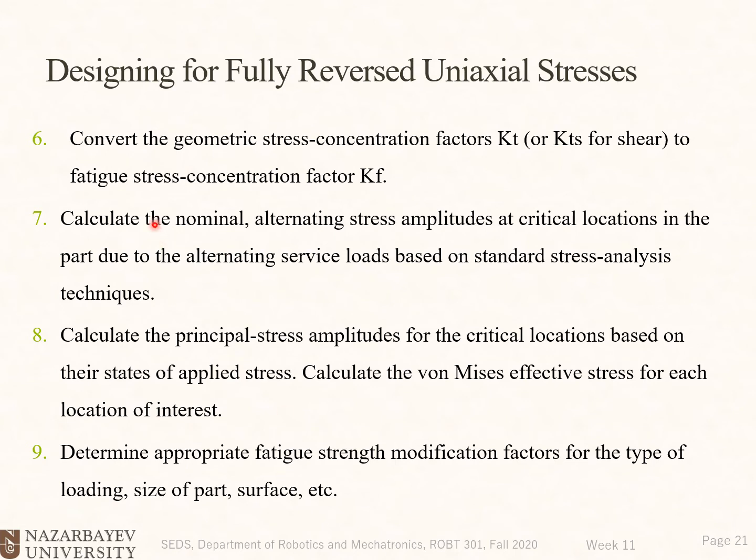Sixth, convert the geometric stress concentration factor KT, or KTS for shear, to the fatigue stress concentration factor KF. So you need to calculate Neuber's constant and notch sensitivity, and finally calculate KF. Seventh, calculate the nominal alternating stress amplitudes at critical locations in the part due to the alternating service load, based on standard stress analysis techniques.